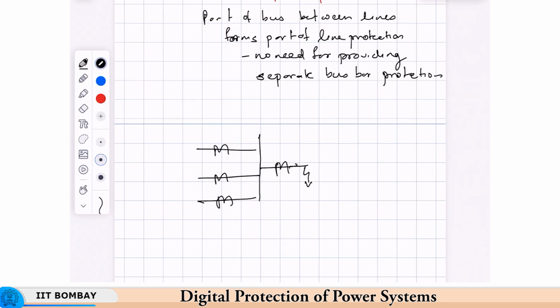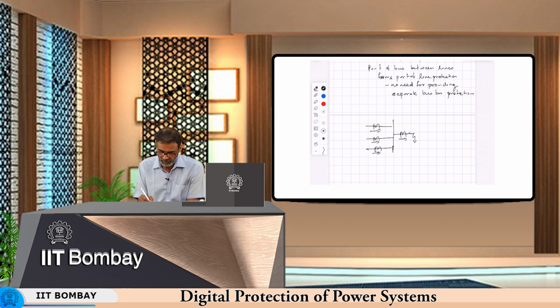Say this is the bus, this is a bus arrangement, and there is a fault here on this feeder. So, this CT will see almost 3 times the current that is seen by the other 3 CTs, and this could saturate on fault. And then the I1 plus I2. So, the fault is outside the zone, because we have seen what happens when the CT saturates. Okay.